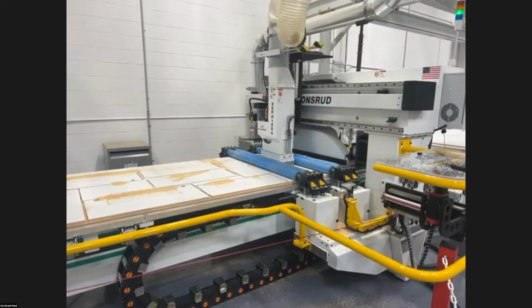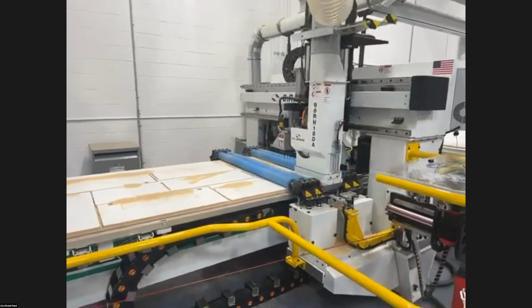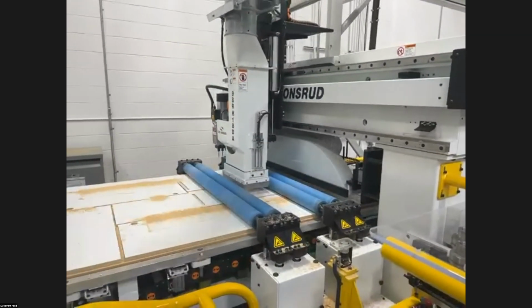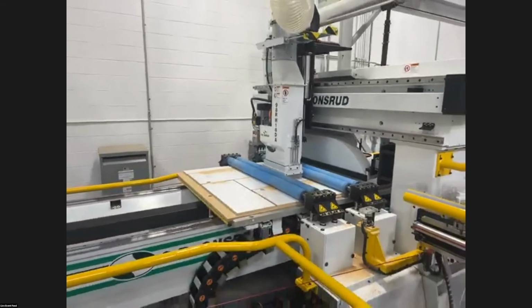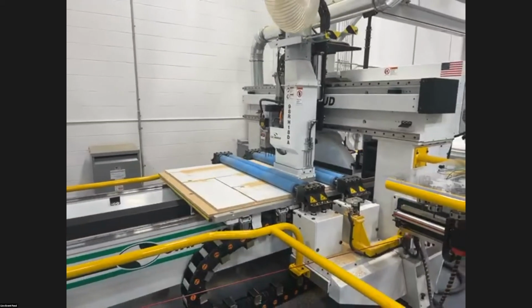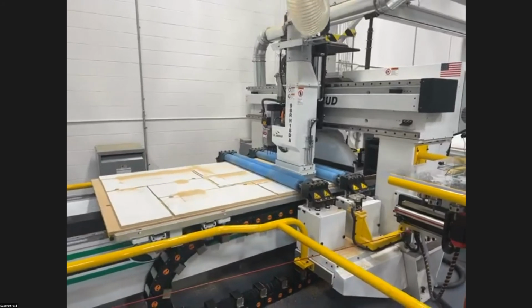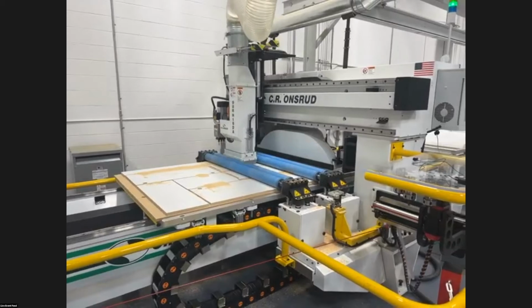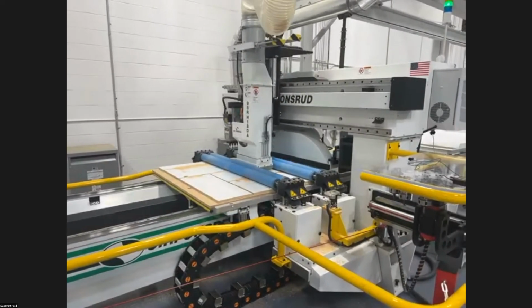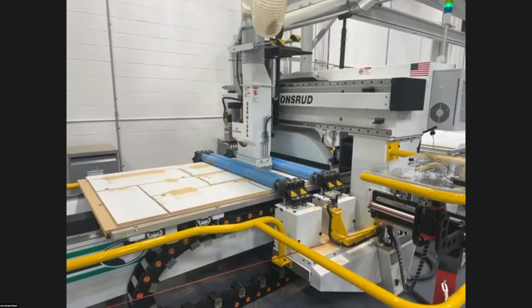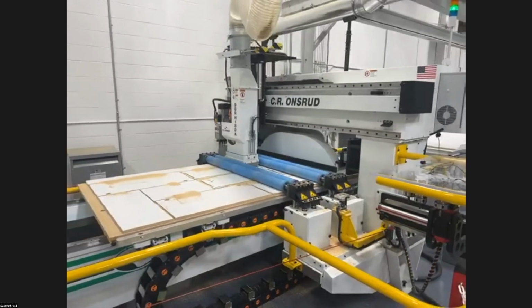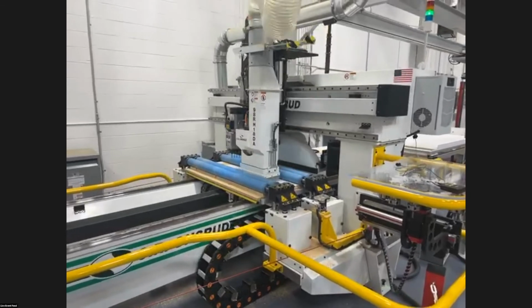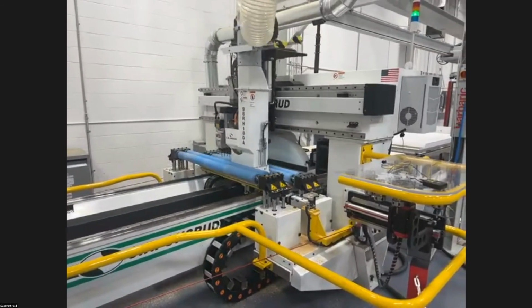So on this model, you notice this is a moving table. The table is moving back and forth. Advantage of a moving table versus a gantry is if you think of a gantry machine, you have all that mass that you have to get up to that cutting speed, let's say the 2000. You have all that mass that you got to get from 0 up to the cutting speed and then back down to make the next turn. With a moving table, you're only moving the material and the table, so much higher acceleration because much less weight.